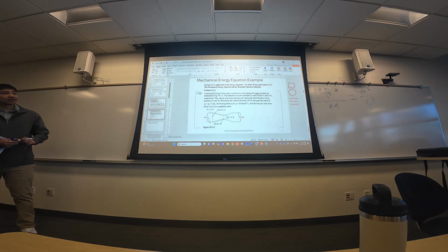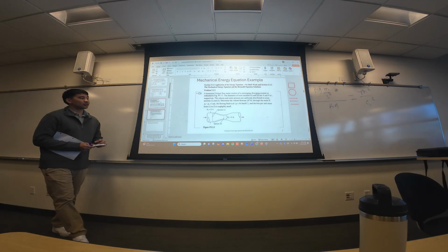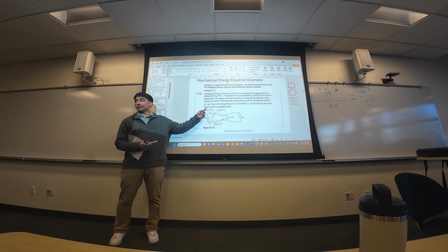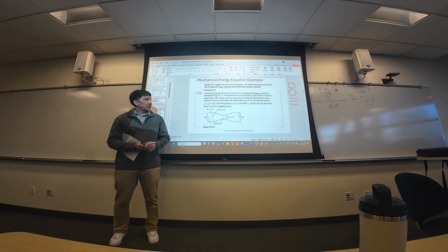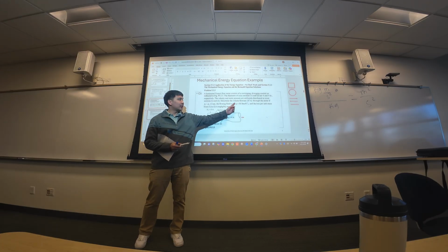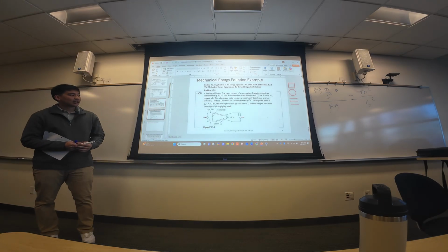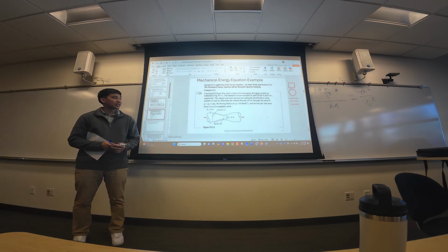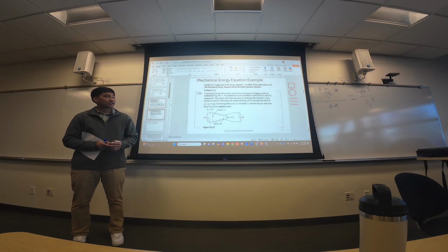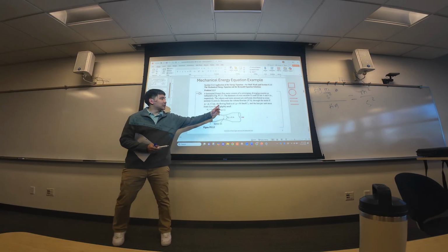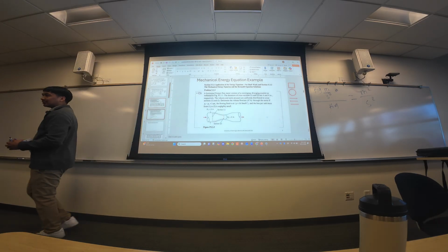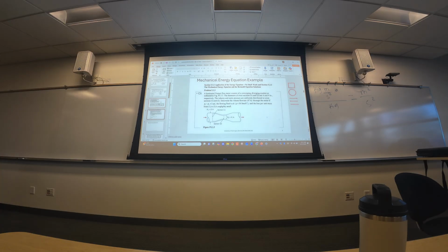The velocity and static pressure are uniform. You have your pressure difference between 1 and 2 here, which is your 3 psi. This should be rho. I screenshotted this from the textbook, but that's your density of the oil. And loss per unit mass from 1 to 2 is negligibly small. So that means friction's not too applicable here. And it's asking you to determine the volume flow rate, which is Q. Similar, you had to use that Q in your quiz, right?